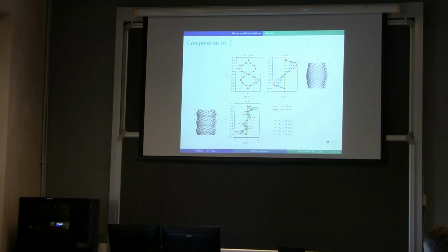If we then connect these two layers by a rotational joint, we can see in this delta theta measure that the outer beams dominate the system, so the shift will happen to the side of the handedness of the outer beams. The dotted line you can barely see because it completely follows the solid line in this case. For the rigid connections, there is a buckling, which was expected because the structure is very, very stiff.